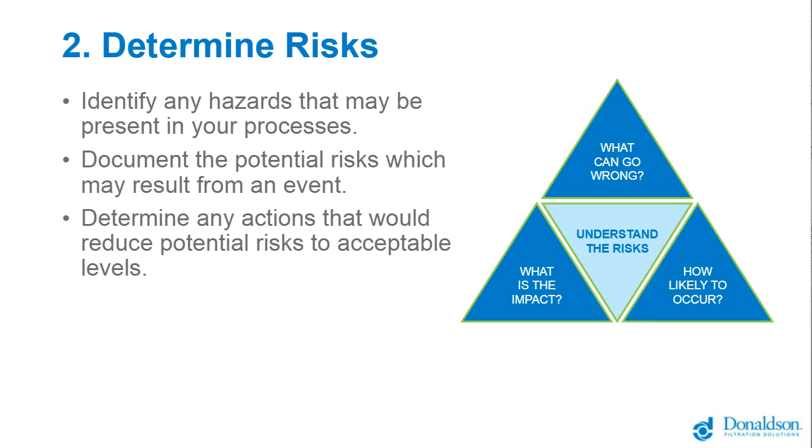To answer this, try documenting the sequence of conditions which result in the event consequence. For example, dust accumulations become suspended in the presence of a bearing which overheats, resulting in a flash fire or deflagration at that location. Understanding this sequence may provide some insights into how to prevent such a chain of events from occurring.